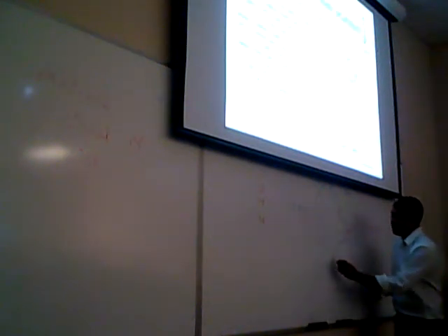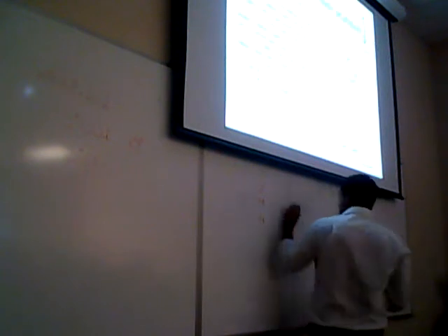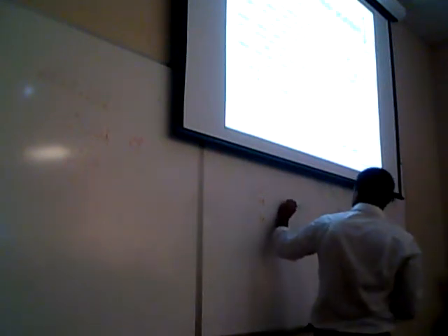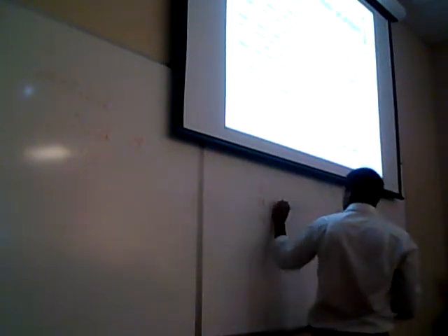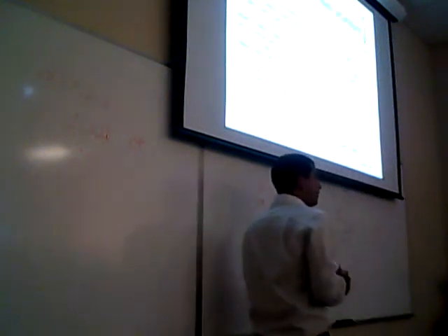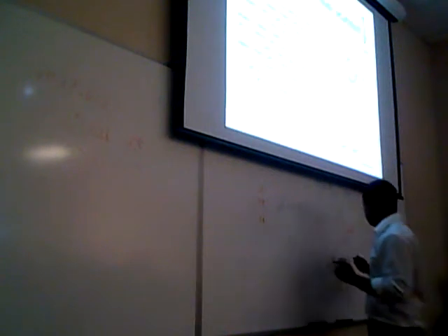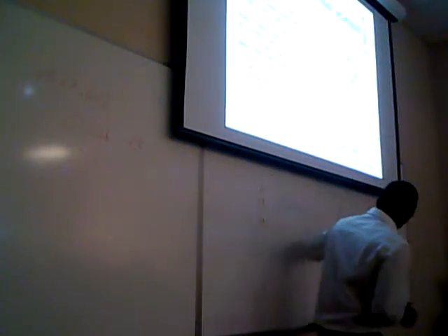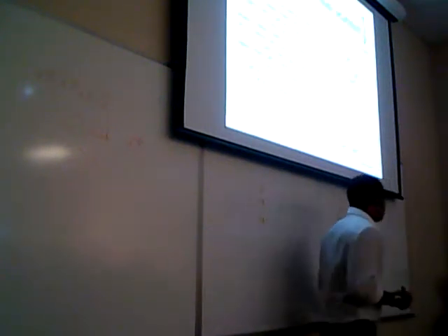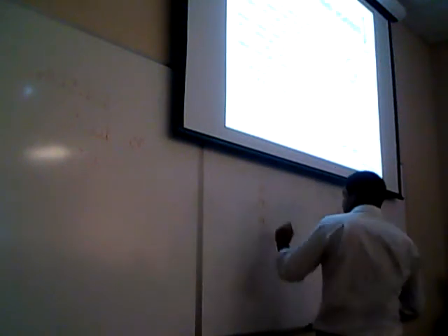So the temperature here is going to be higher, so we know that at this point the density of the water is going to be lower. The temperature of the water at this point is going to be low in comparison with this point. So there is going to be a natural recirculation of the water. This is the principle.